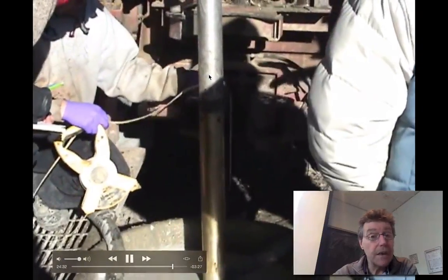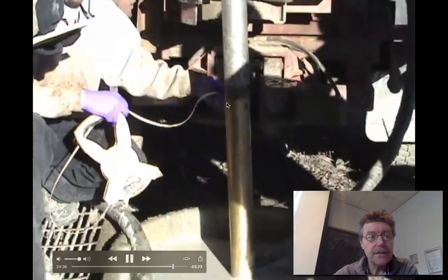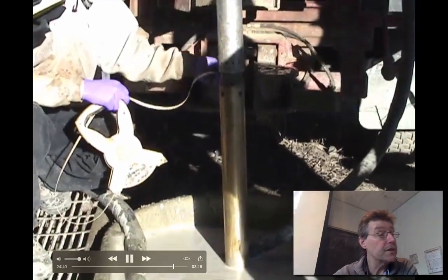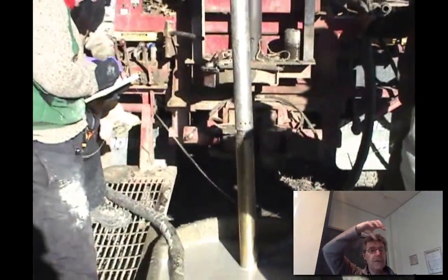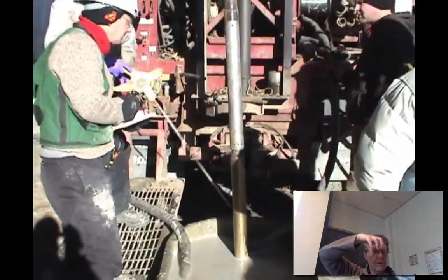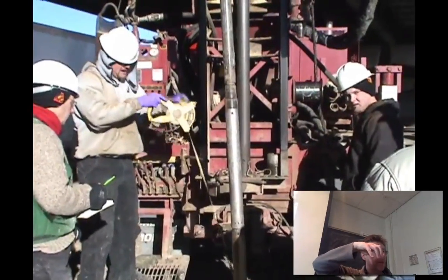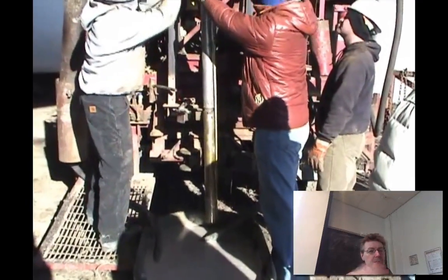This is a piston sampler, and basically it has a piston that gets advanced to the very end of this tube, which expels all the water that's in the tube. The whole assembly gets put on the bottom of the borehole, and then the tube is physically pushed into the soil at the bottom of the borehole, but the piston of the syringe stays on the bottom and rises relative to the brass tube.